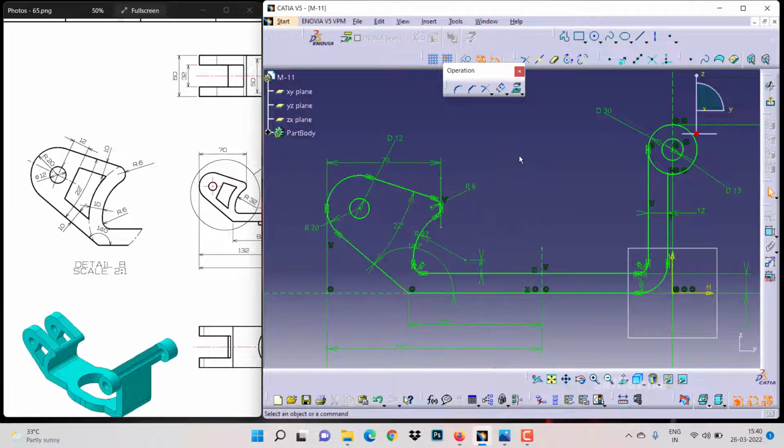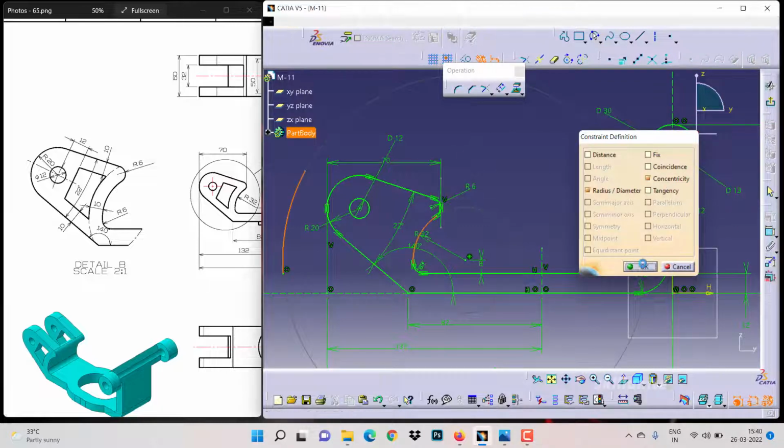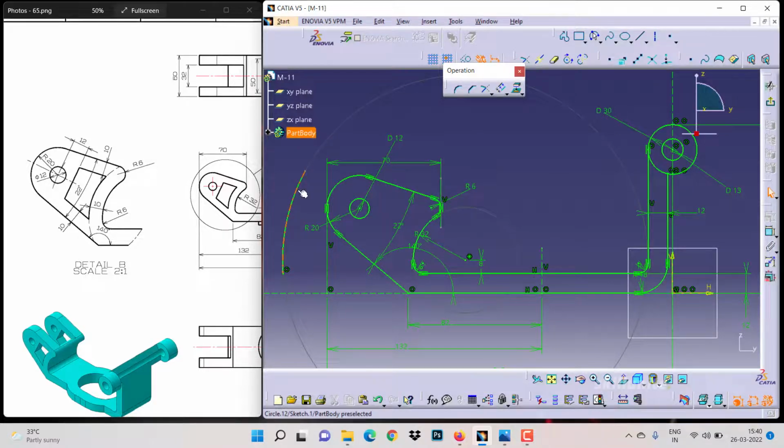So I guess we have to create it on our own, then we will make the distance. So we will just create a shape, simply a reference arc type we will create it. Then we will make concentric to each other. So then we will keep the distance, so that it will be easier to create it. So as it is added one more constraint over here, tangency, because of that it is not moving frame. So now once I delete it, I can move it any closer nearby. So then I have to keep the distance, so that is 10 mm. So click on dimension. So select the arc 1 and arc 2, dimension 10 mm.